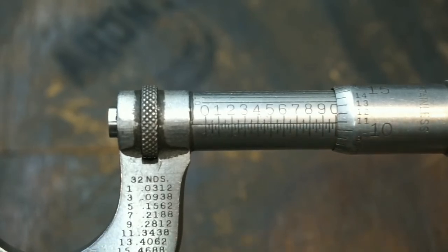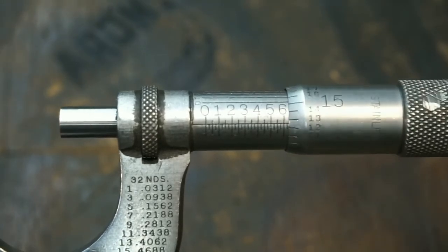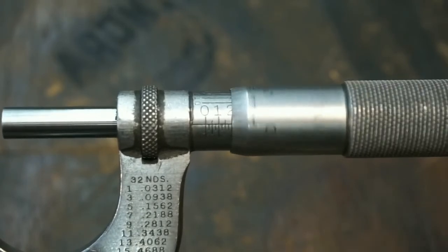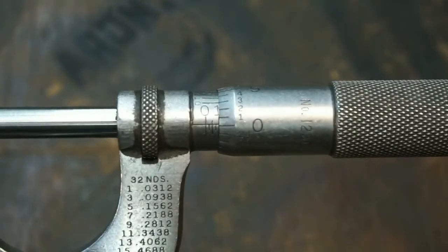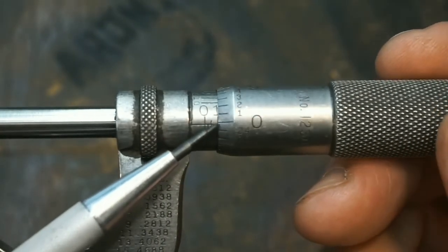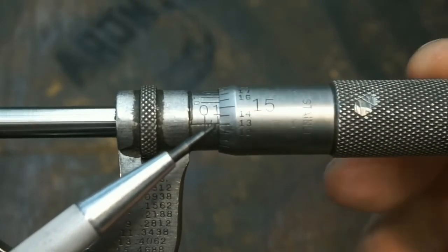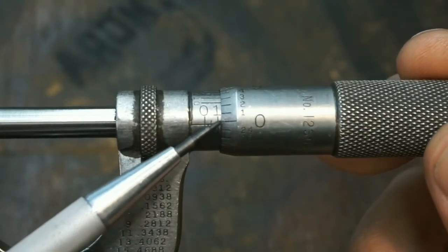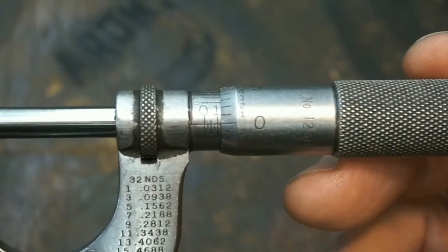All right. So let's go ahead and we'll run the barrel in just a little bit here. We'll bring it on in so that's a little bit easier to see what's going on. So let's go to, we're going to go to 100. I'm going to line it up on a 0. But what I want you to know now is all of these numbers on a barrel. You see we start with 0 and it counts, 1. And as we go all the way around, you're going to end up, there's 24 and then there's 25. So each revolution of the barrel is 25 thousandths of an inch.